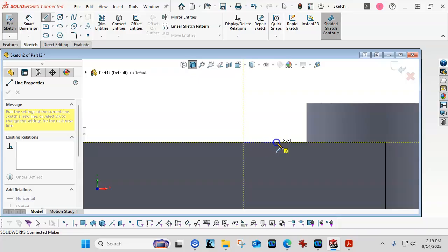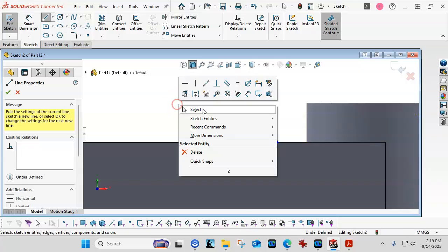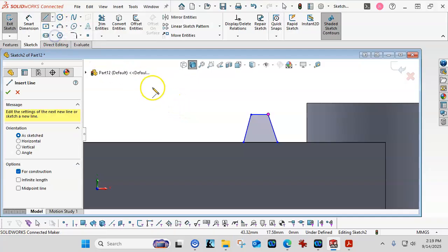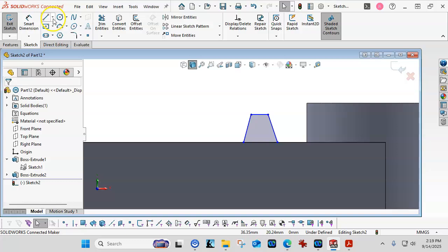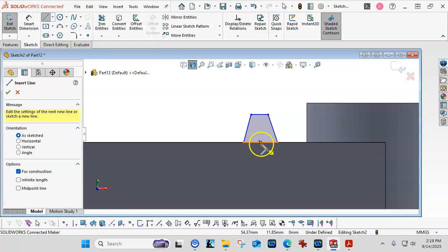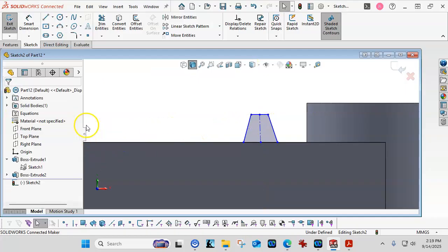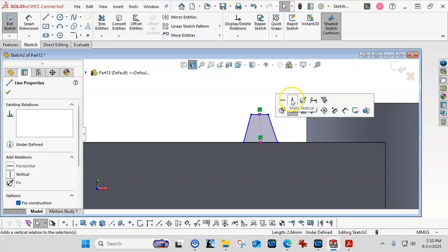Okay, so I'm going to start with a line across the bottom. So I picked up coincident. I'm going to coincident and bring this back around. All right, so this is able to move side to side, so we're going to have to choose how we want to manage that geometry. Usually, I'll go right into center line. So underneath line, center line, pick the midpoint, and then we'll escape out of that. And I just want it to be vertical.